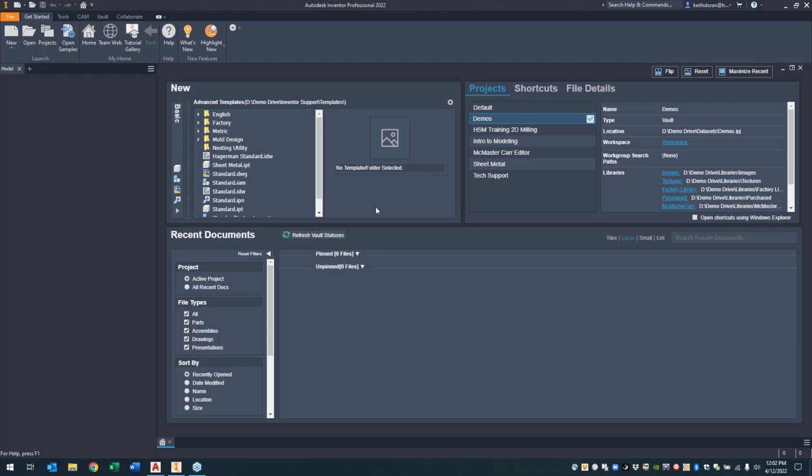And the first big thing to think about is we're working in a brake press type of environment, or a very basic die form type of environment. We can't really do progressive die stamping. We can't do necking operations within the system and flatten those components, at least not yet. We do have some new functionality available to us to help get us some at least basic understanding about how a component might flatten, creating heat maps of that networked flattened component. I'm not going to be talking about those today unless time allows at the very end of the presentation.